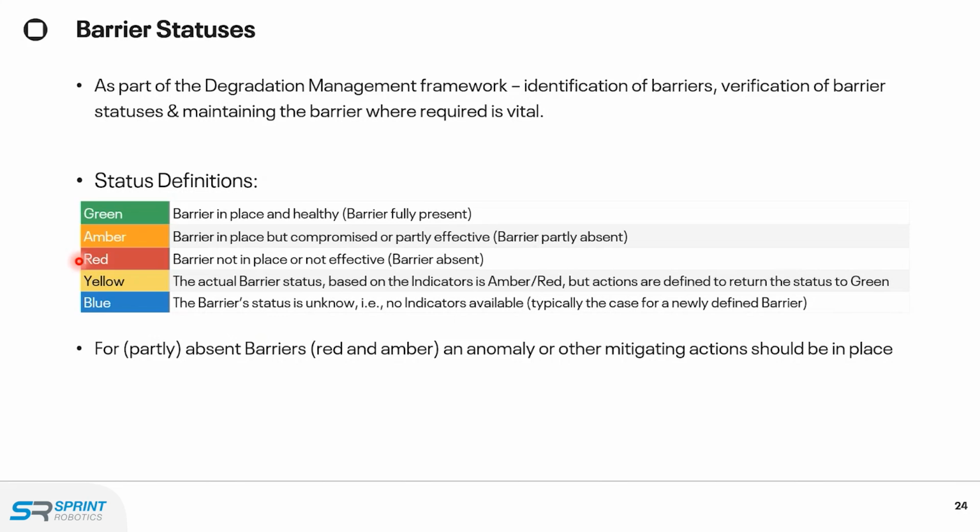So when I change the status to red, we're going to show that the barrier is red to all the components within the same corrosion loop and say, listen, one of those equipment had an issue with coating. You have to pay attention, because likely this degradation will also happen in other equipment in the same loop. If you fix that barrier but you're still pending an action, we can bring in yellow. But the objective is always to bring it to green. Evergreening is the word. And whatever you don't have any data for is going to be blue.